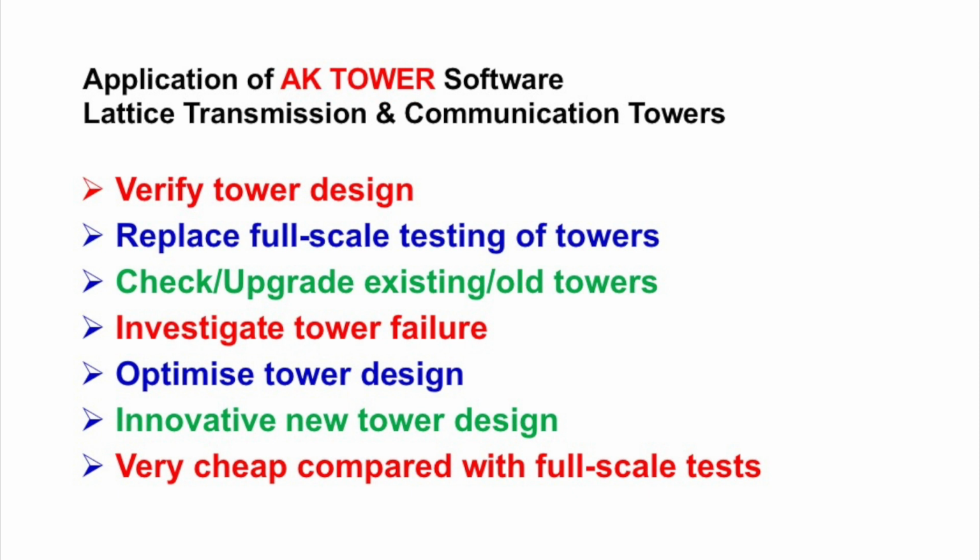We've done a lot of consulting jobs. In fact, we have simulated all the tower designs in Australia, New Zealand, and some in the UK and so on, to the point where a lot of utilities now believe in us and don't do full-scale testing, because the software can be used to verify tower design. In fact, the full-scale test cannot capture the real behavior because the load cannot be a free load. The load is a follow load. So you can never test the tower in reality.